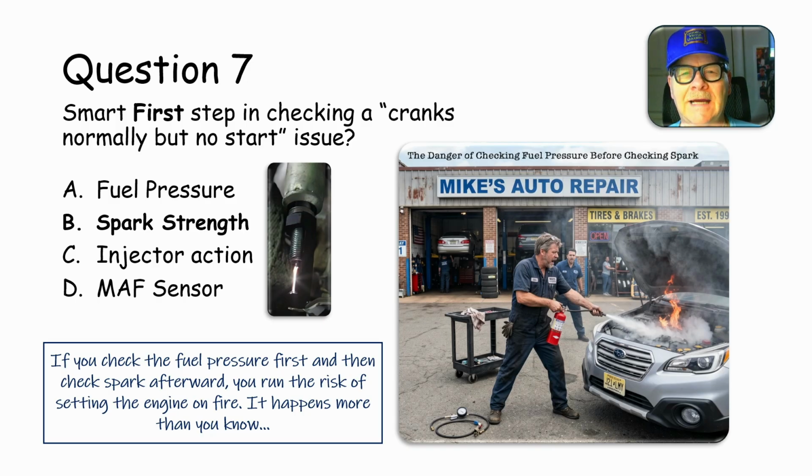And so he wasn't all that familiar with these Jeeps. He had worked on other makes, but he never worked on Jeeps. So he was going to say, I'm going to pull the plugs out, and I'm going to just spin it over and let it blow all that gas out of there, because those holes are kind of pointing up anyway. And so he unplugs the distributor, which is the cam sensor, which on that one is not going to keep the ignition system from working at all. He spins it over, and of course it's sparking while all that gas is coming out.